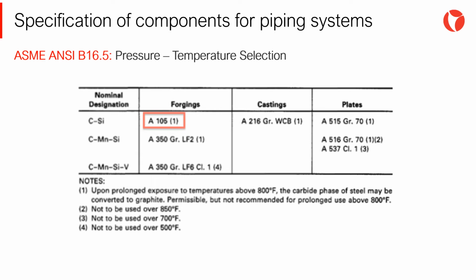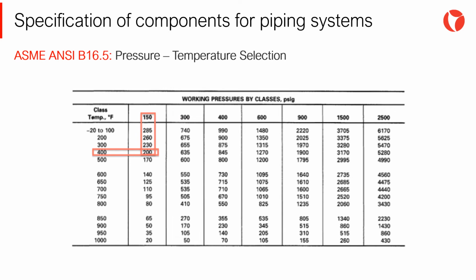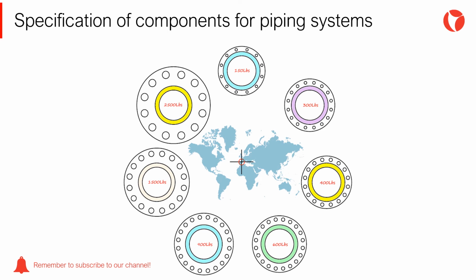When using this flange standard, the first step is to find the adequate chart for the flange material required. Then, the pressure class, or rating, must be determined from the pressure temperature range corresponding to the flange material. In other words, we need to select how strong the flange should be to withstand the pressure and temperature effects.